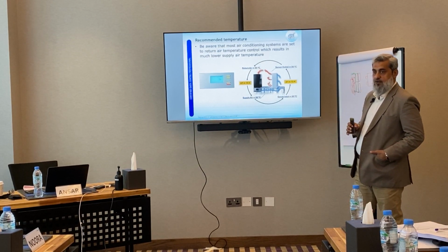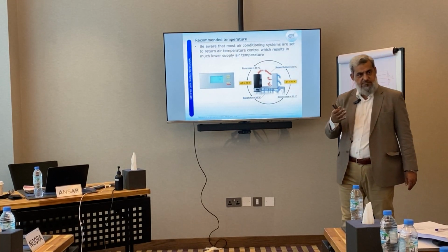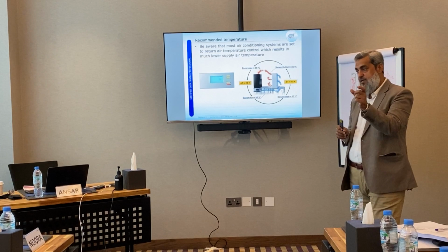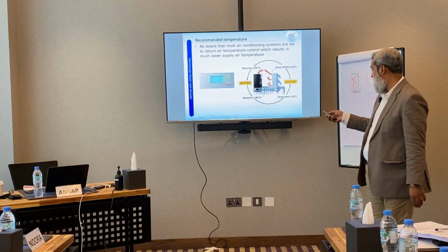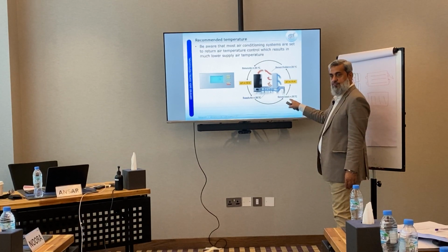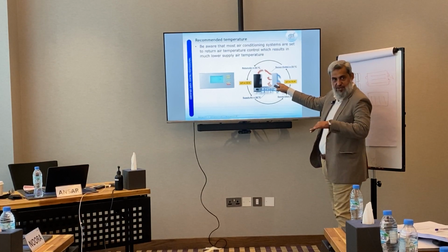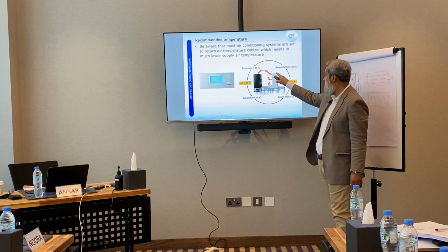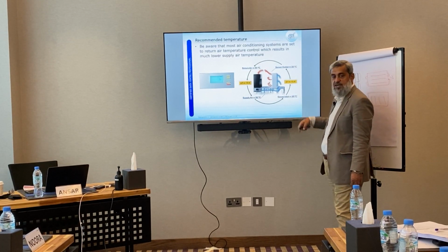So what is delta T? Many people would be aware, but delta T is the difference between the temperature of the cold aisle and the hot aisle. The difference in the temperature. So you can see here, if we are giving server inlet 20 degree temperature, 20 degrees is going into the equipment, it passes through the equipment, and here you can see the temperature could be say 35. So the difference of these two is called delta T.